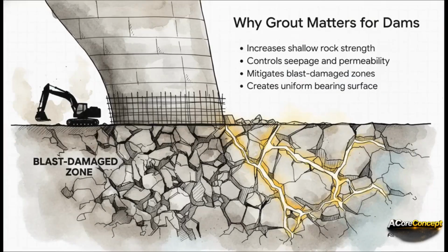And this process is absolutely essential. It increases the strength and stiffness of the shallow rock mass. It controls water seepage by reducing permeability, and it creates a highly uniform bearing surface for the concrete. But a really crucial takeaway here, and something you'll definitely encounter in the field, is mitigating blast damage zones.